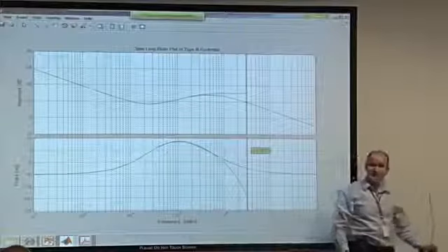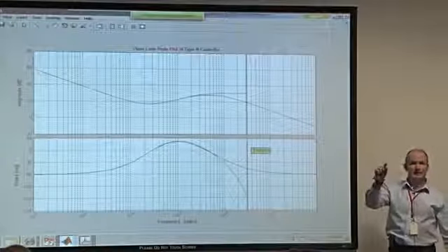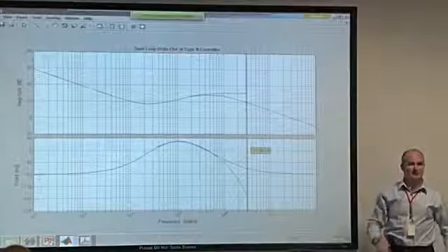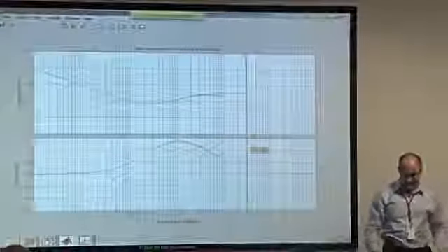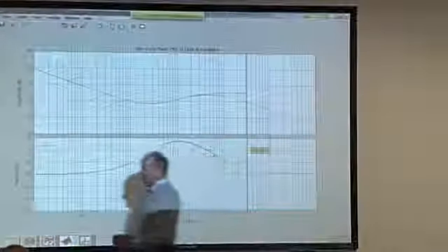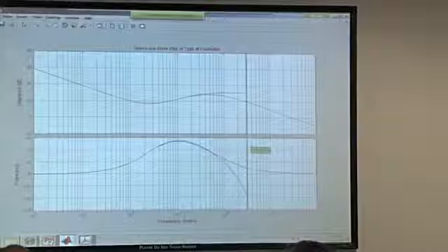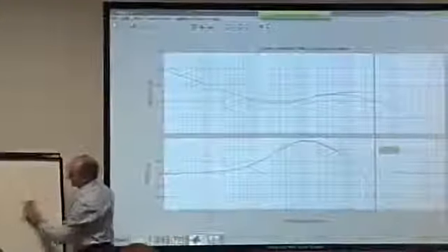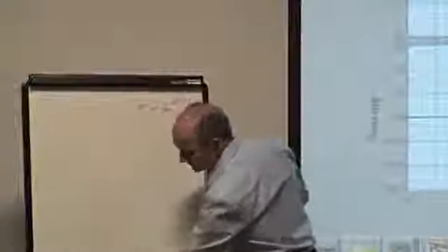But it's pretty easy to use, isn't it? You just take every instance of s in the transfer function and replace it with z minus 1 divided by T. I mean, what could be simpler? Well, the forward approximation technique has a problem. And the problem doesn't immediately strike you until you see an example.